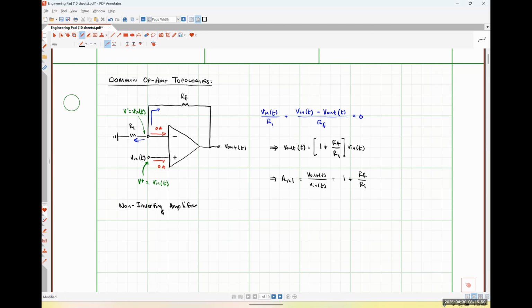So if we had something like a simple piezoelectric crystal, or maybe a small scale pressure sensor that could generate a reasonable output voltage but can't really supply any current, we might pass that signal through a unity gain buffer to use the power supplies for the op-amp to provide any current that is necessary to drive a connected load.